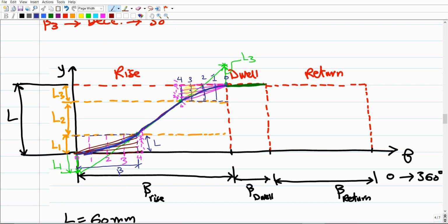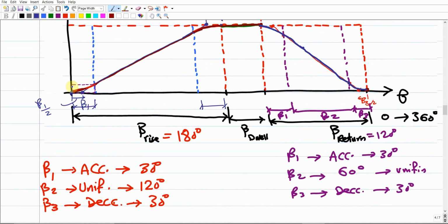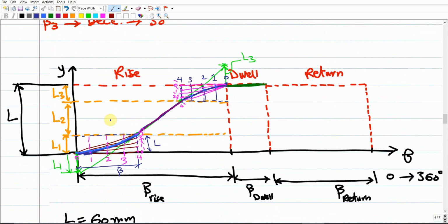Why did I divide this one into different segments, and I didn't do that up there? Simply because this zone is very small, a very narrow zone to do the division. So it is acceptable if you connect it directly there, but for this one it is a wider zone, so we have to break it down and divide it into different segments, following the approach as I explained, for representing this parabolic motion in the accelerating period and the decelerating period. Make sense?